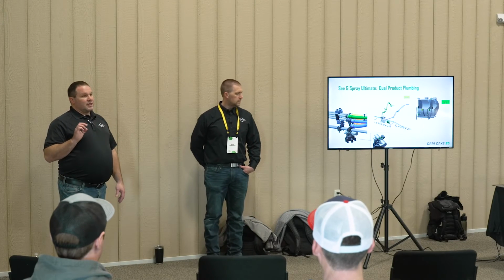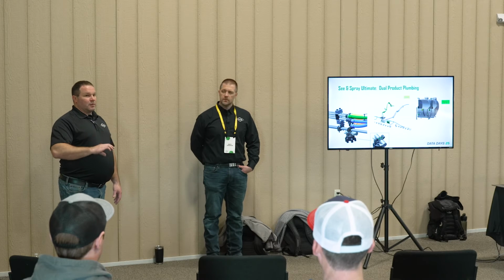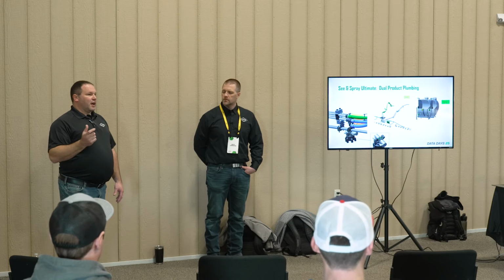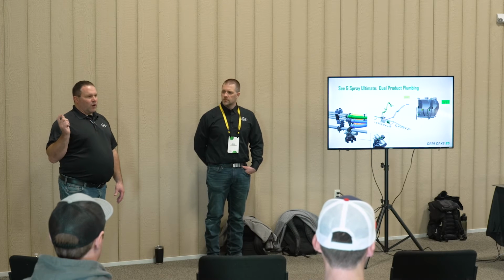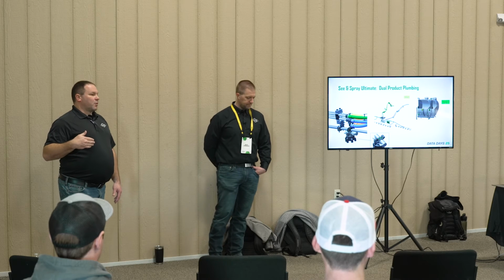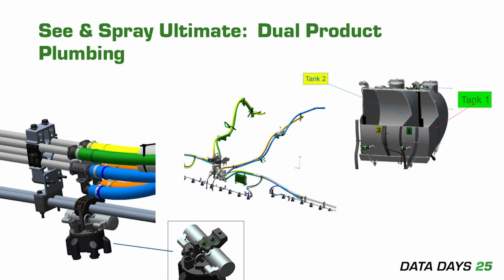Our See Spray Premium, the machine we talked about and the machine that's sitting behind us, is our regular solution system. Our nozzle body is fed with one line where we can do recirc and reclaim on it. We think of Boom Track Pro Ultimate, right? We have two solution systems, so we have two lines feeding every nozzle.